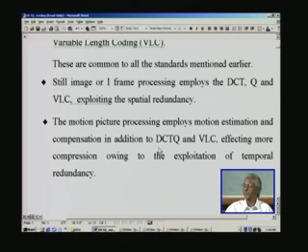If you want to find the motion between two successive frames, you have to take one block, known as a macro block, consisting of 16 by 16 pixels, and search in a window which is 4 times that area in the previous frame, so as to look for where the particular macro block has moved with reference to the previous frame.